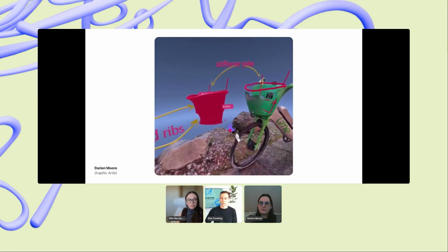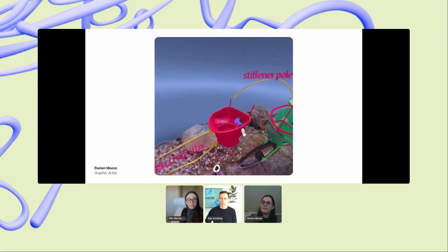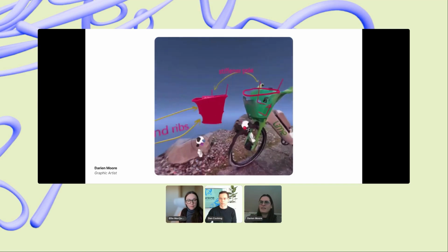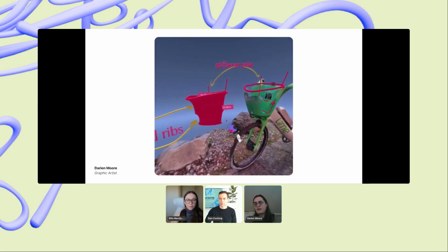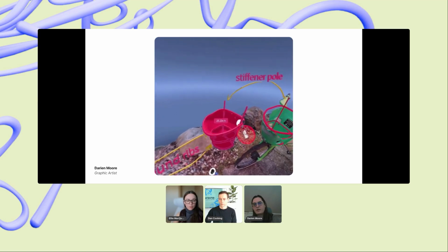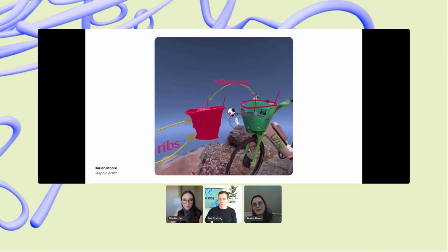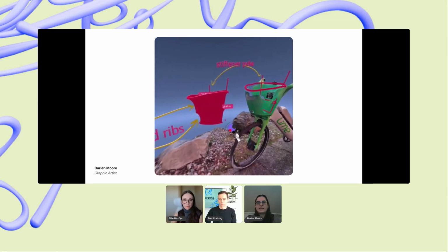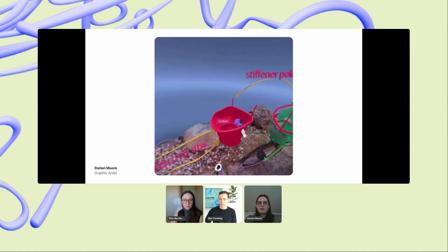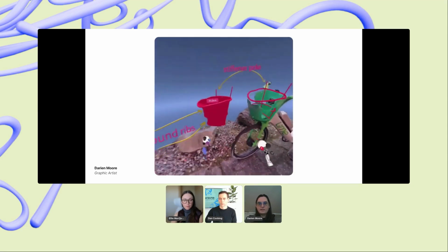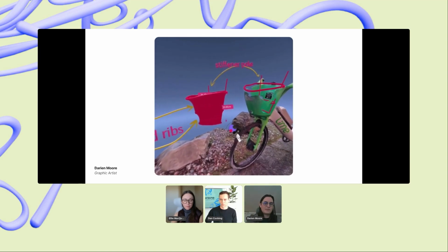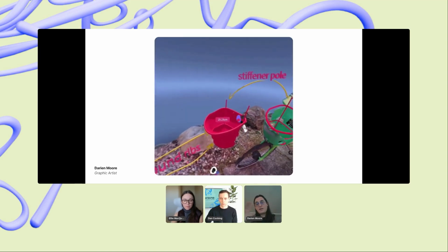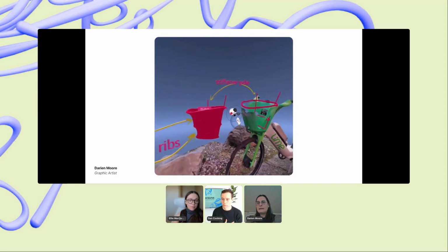I hope everyone here is familiar with Gravity Sketch. The little grabbing cursor won't grab or highlight the scan, which, if you're on one of the older Quest 2s like I'm on, keeps the frame rate higher if you're not interacting with a grabbable object. So lock that, make that not movable, and then do the same thing with the horizon lock, so you're not getting flipped around.